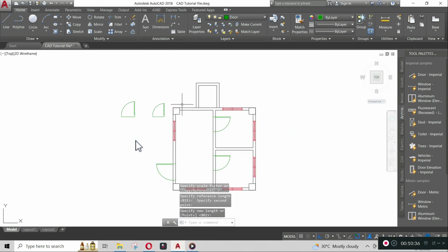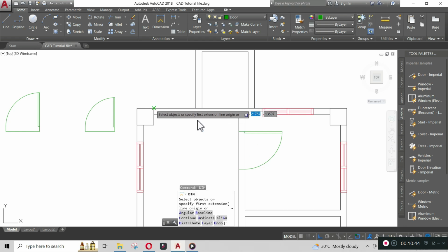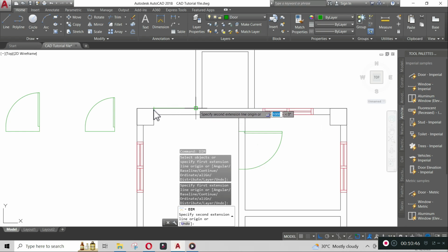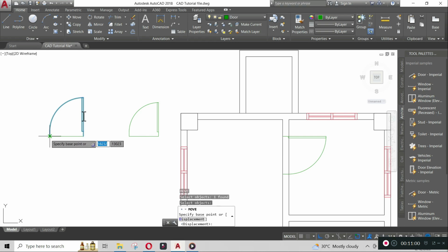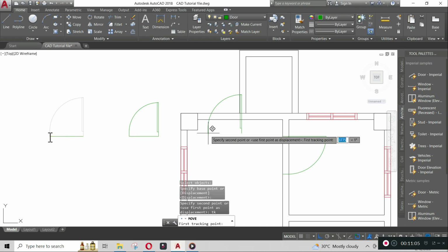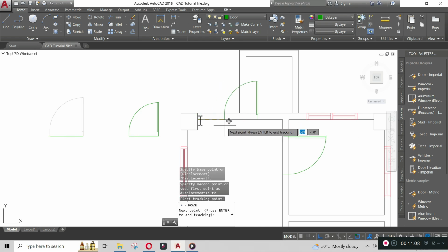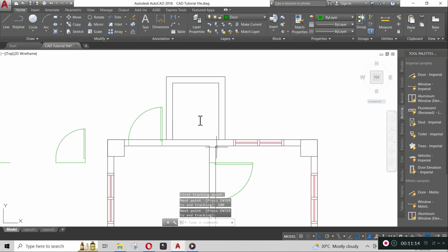Now move the door and place it at the center. Use dimension command to measure the distance and move it at the center. To do so, type DIM, and click enter. It is 1000 millimeters. Since the door width to be placed is 800 millimeters, therefore we will have a moving distance of 100 millimeters. Do the same process for the 700 millimeters door width.